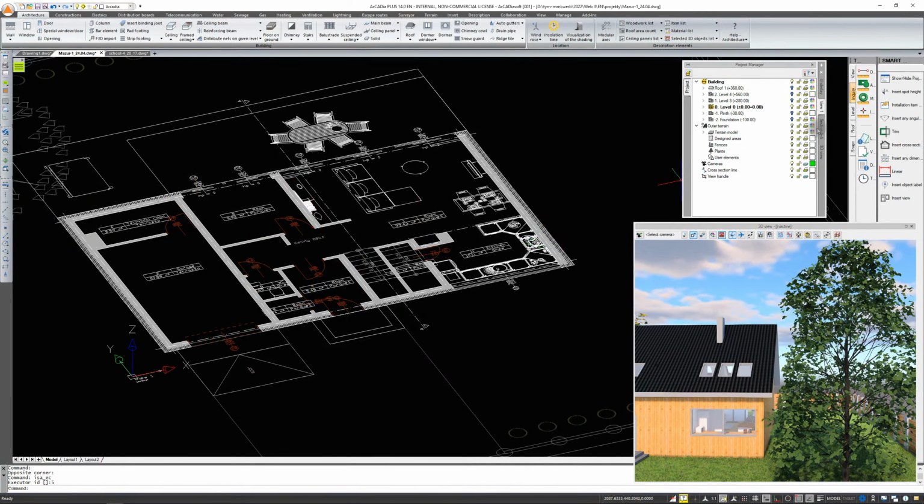So you click on one view and with the mouse right-click and choose Delete. Or we switch to a given view and just turn off all the light bulbs. But of course, remember that if you turn off these light bulbs, the program sends this information to this view anyway. So at some point, it will slow down your work anyway.